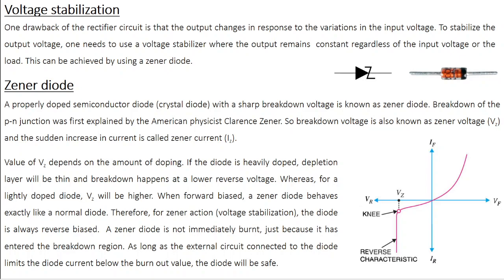So we know the general working of a diode, or the typical VI characteristic of a diode, right? Here, during the forward bias, you can see up to the point where the biasing voltage exceeds the barrier potential, you do not have much current flow, but once the barrier potential is crossed, you have a considerable increase in current along with the increase in the biasing voltage.